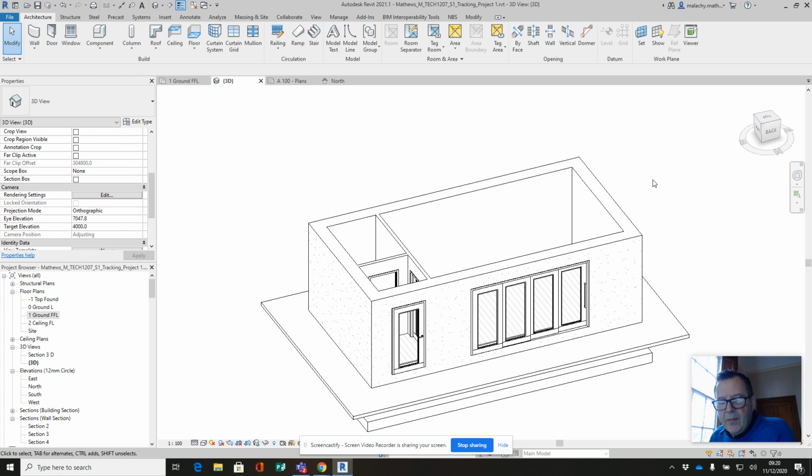And there are several elements to this. First part is we're going to go into our roof command, obviously over here in the architecture tab, and we're going to pick this roof by footprint. That'll give us access to the properties here. We're going to go and choose a particular roof system family. We're going to inspect the structure of that. If it's not suitable to us, we're going to duplicate it and we're going to change around some of the elements to that so that we get a roof which is suitable for this particular project.